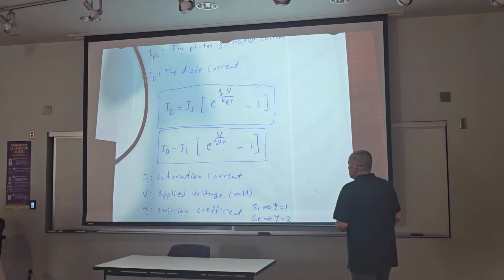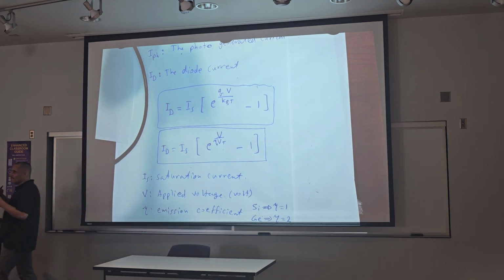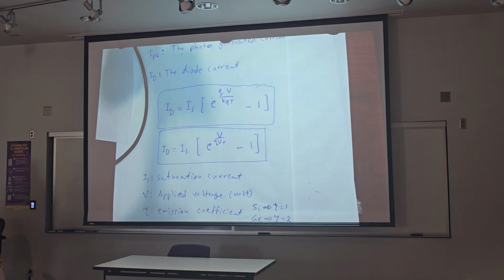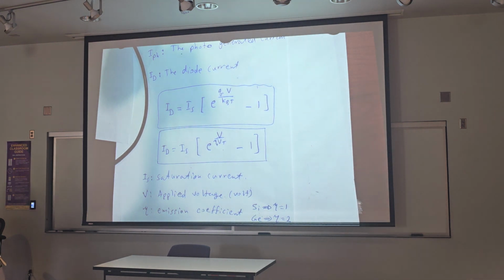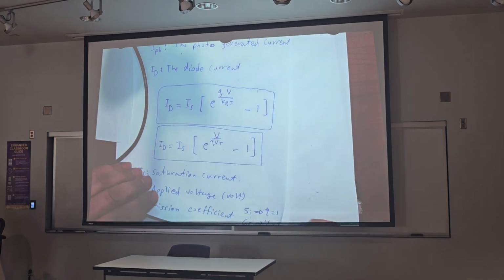Okay? Now, VT, what is meant by VT? This is the volt equivalent to temperature, equal 26 millivolt or 25 millivolt. Some references take VT as 25 millivolt, and some references say 26. Why? Because it's 25.65, so approximately 26 millivolt. This is VT.